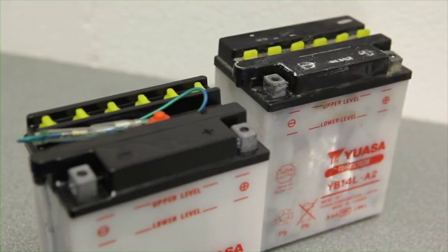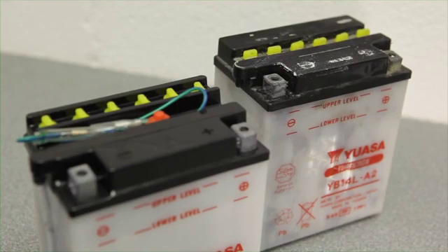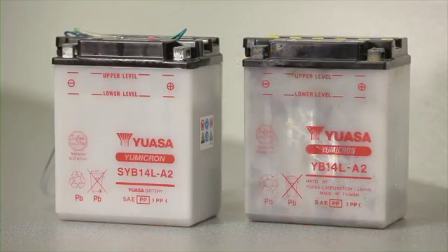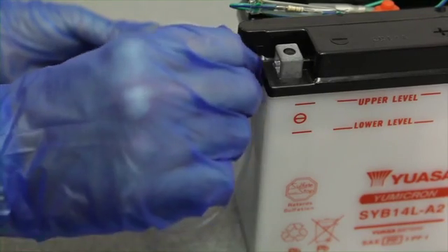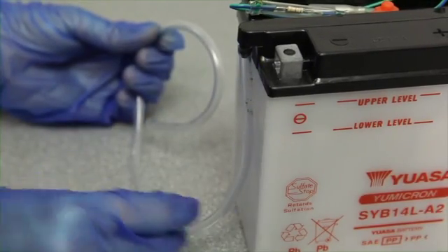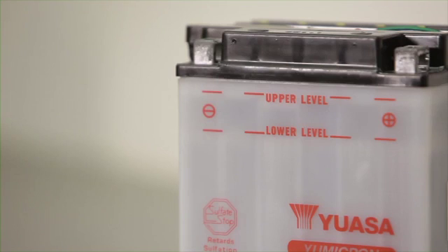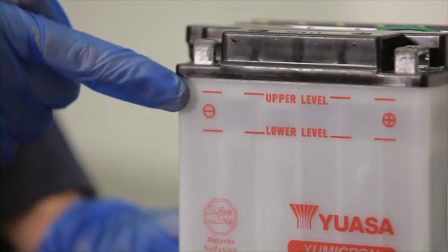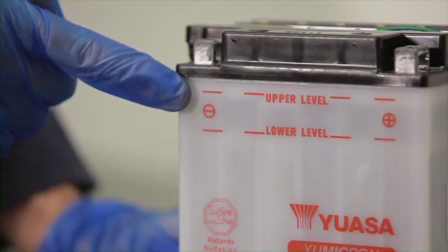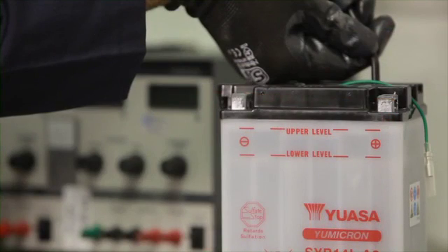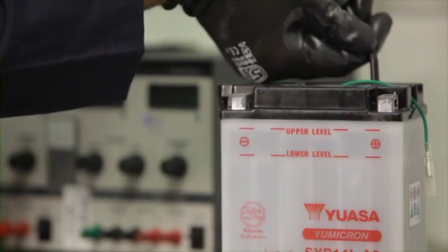This includes regular checks to make sure the top of the battery is clean and dry, inspecting the battery terminals, connections and cables for corrosion or damage, and ensuring all the connections are tight. The outer case should also be checked for cracks or signs of leakage. The routing of the vent tube on conventional batteries should be correct and unobstructed. For conventional batteries, the electrolyte levels should also be monitored, using distilled water to top up cells as required.